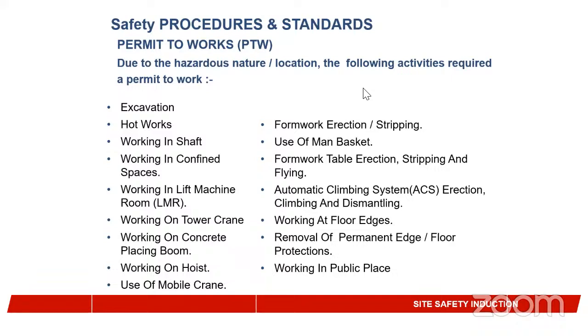Because the permit to work can be issued after an induction, after the toolbox talk has taken place. The toolbox talk serves as the key to having your permit to work. If you have done your toolbox talk, submit it, and your name is included. Even the supervisor who is addressing the job, who owns the job, must not engage someone whose name is not in the toolbox talk to carry out any activity, because it is what guides them. So it assists in so many ways.